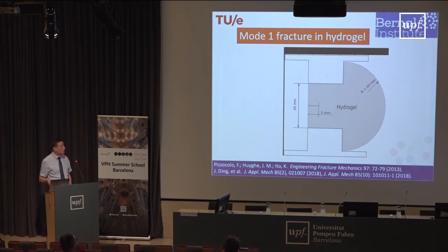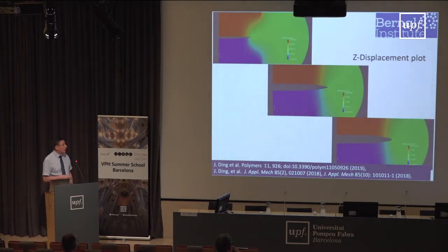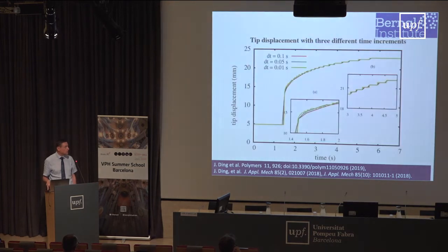Now, we go back to our experiment. Our experiment is a hydrogel with an initiated crack, and this time we simulate in finite deformation the propagation of the crack inside the gel, and we can plot displacement or pressure. We have a propagation of a crack which is definitely, as you can see, in the range of large deformations.